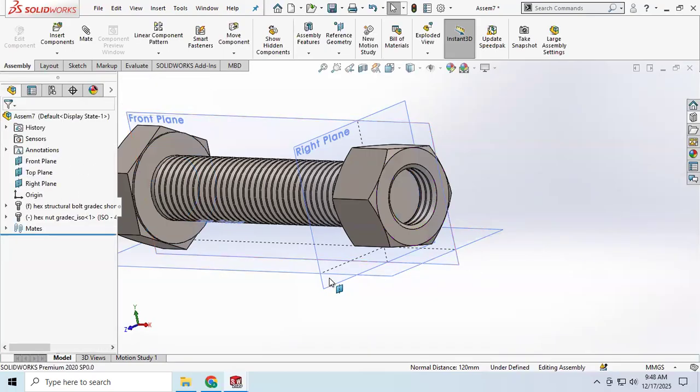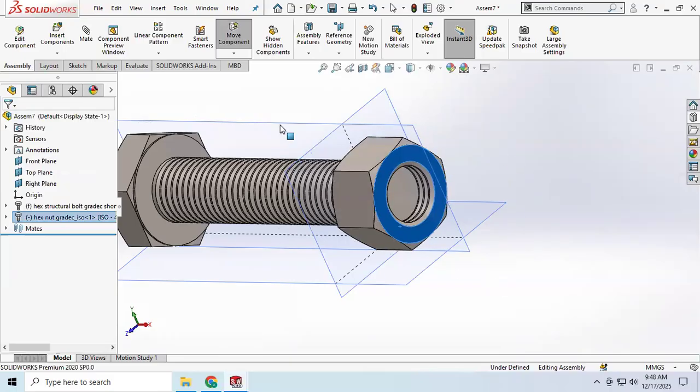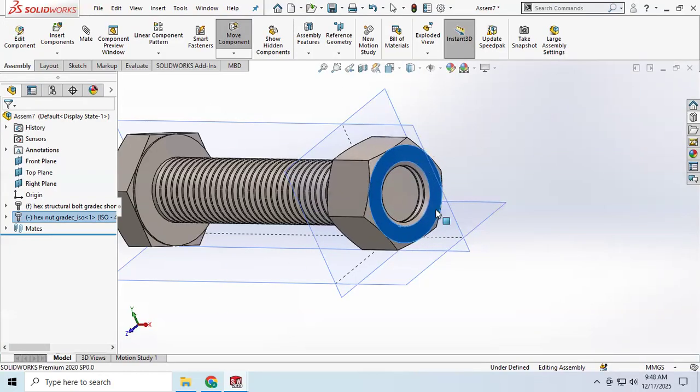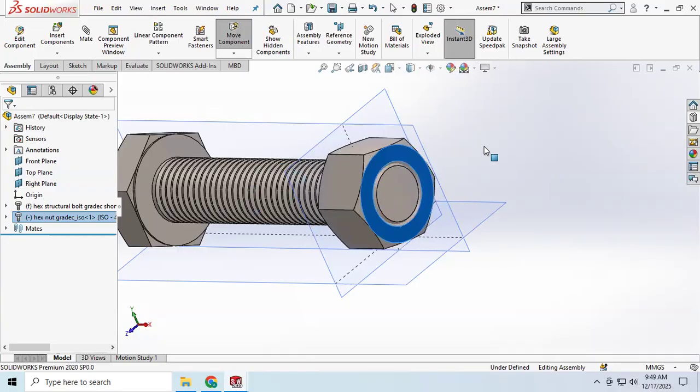But you have to set the width right there, because this position has to be set before making this type of mate. But this is better. Yes, this is called a screw mate, where you can use it like a screw to move it like a screw. By this way, you can create a screw mate right here. Just create this point and create it inside, and this will work like that.